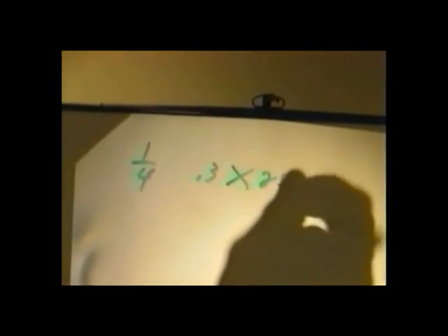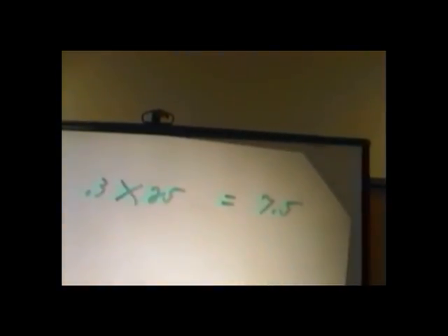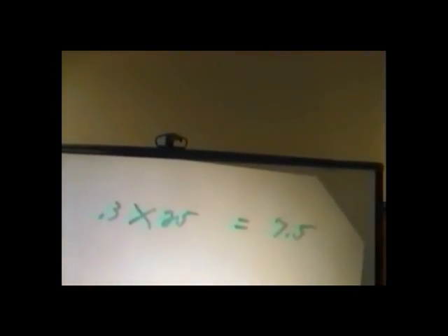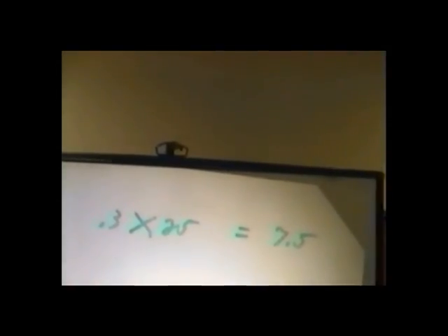You watch me, because sometimes I make mistakes on this. If we have a 1/4 inch line, and we said that that is 0.3 ounces per foot, that means already included is 0.3 ounces times 25 feet, and that would equal what? Isn't that 7.5 ounces? Yes. So that's already included in the data tag charge, okay?